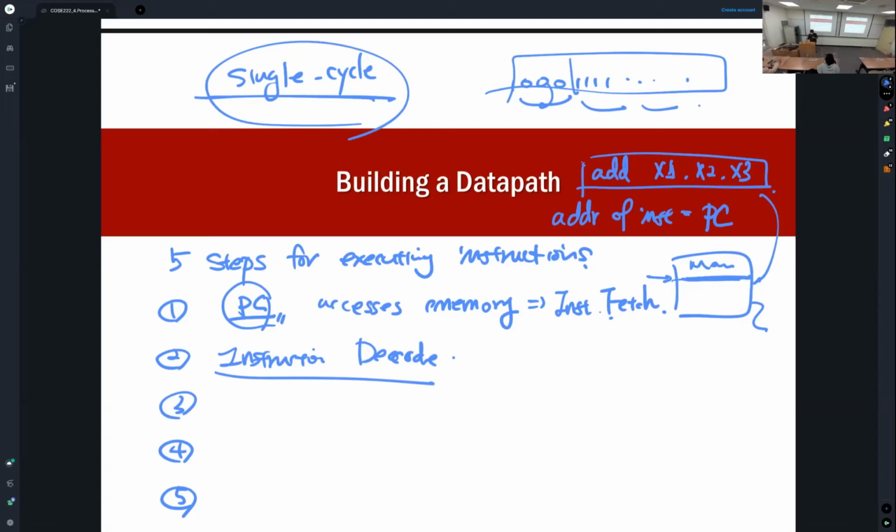For example, this is the add instruction, add x1, x2, x3, and this is the R type instruction. We learned that this instruction has the opcode field, the RD field, function 3, RS1, RS2, and function 7 fields, right? By checking the bit data in each field, a processor decodes the instruction.